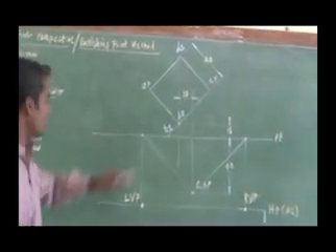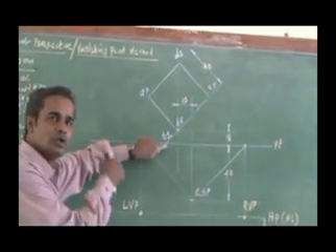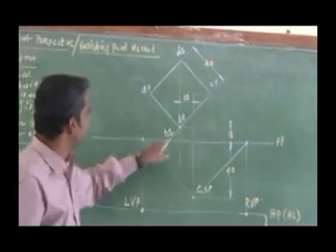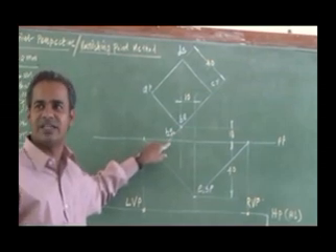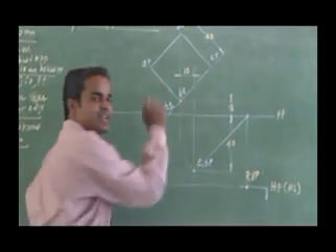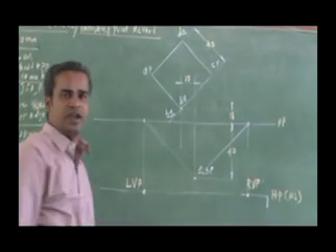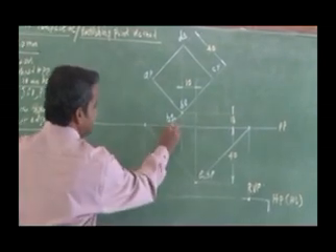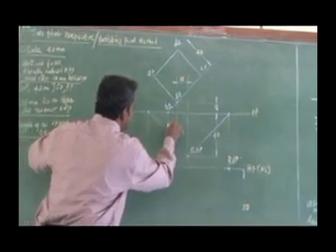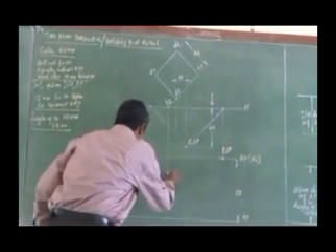Now if I project this B2, Q2 to the ground plane, that B2, Q2 edge will give me the true height in my perspective, isn't it? Since none of the edges are touching, I am extending one vertical edge either parallel to right vanishing or left vanishing to get the true height. Parallel to the right vanishing I have extended, I have marked B2 at an arbitrary location. Then I am projecting that to the ground plane.